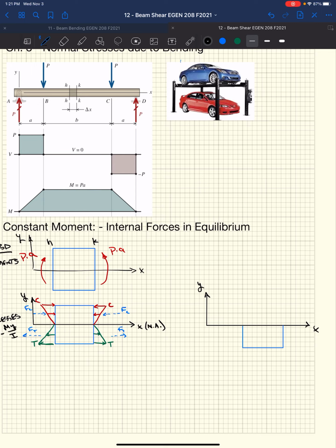So we take our little free body diagram we made showing the internal stresses in our cross section. Right? Those stresses act over an area, which means we have essentially a force acting above and below the neutral axis on each side of our cross section. And now I'm going to cut it at the neutral axis and look at what's going on at the neutral axis surface.